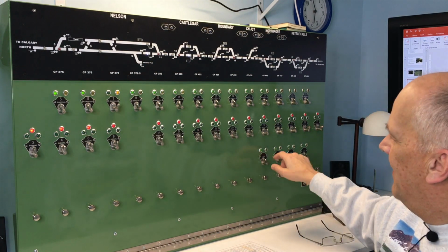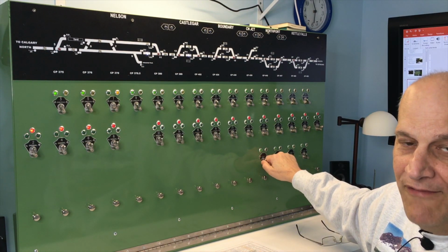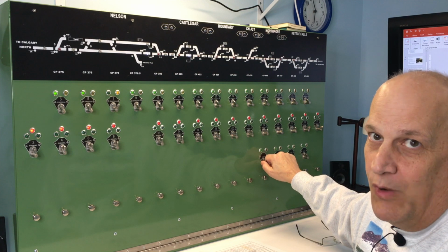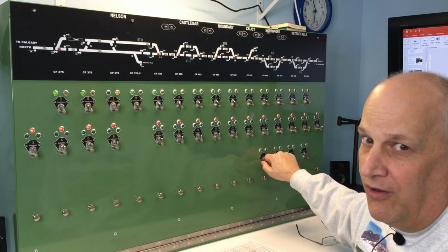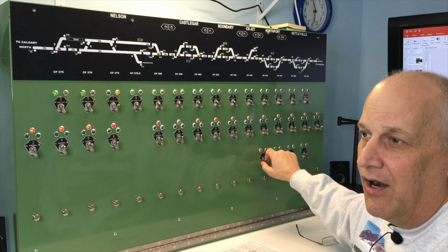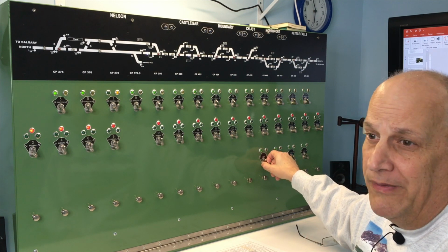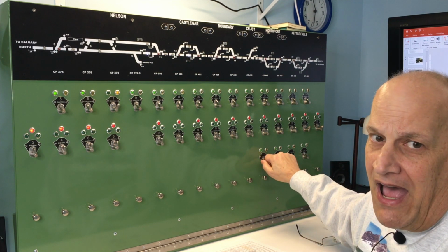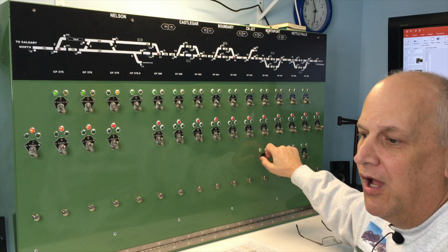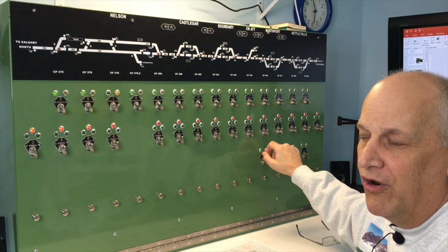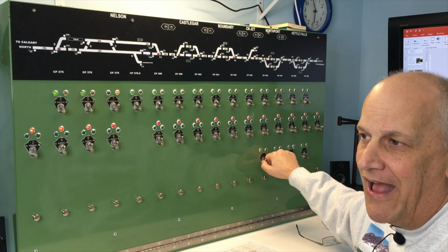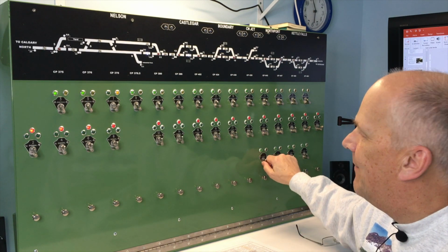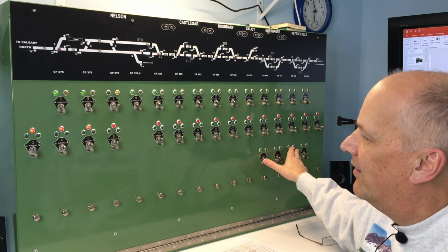The other thing on the machine is there are a few levers here for locking switches. So we have a couple of areas on the CS&P where turnouts need to be under local control because of local switching that is done there. So these levers here provide for the dispatcher to put those turnouts into local control, where they're controlled by the local crews on the fascia and no longer under dispatcher control. So that's what this bottom set of 4 levers are for.